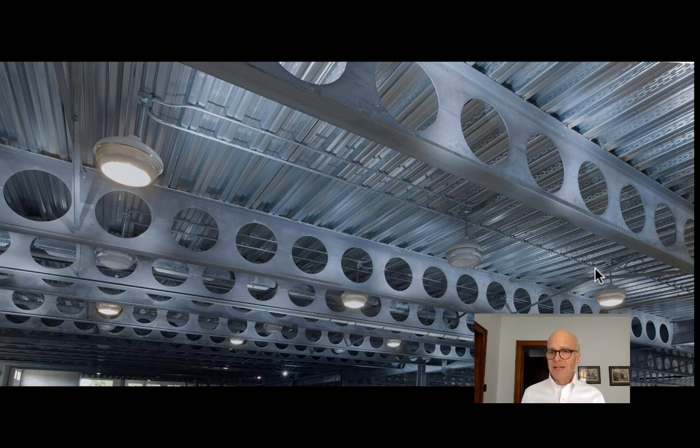This can be part of the aesthetic to the building. It was sort of a standard trope in high-tech architecture that you would use these kind of castellated beams and express them to show the structural principle at work. And of course, mechanical engineers love castellated beams because there are lots of places to put small ductwork, pipes, things like that, right? The holes around the neutral axis are very, very convenient places for those kind of mechanical things.